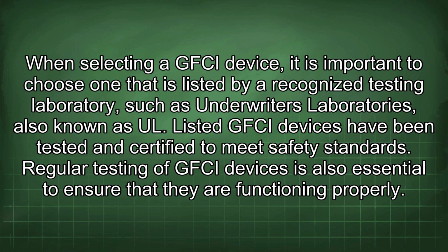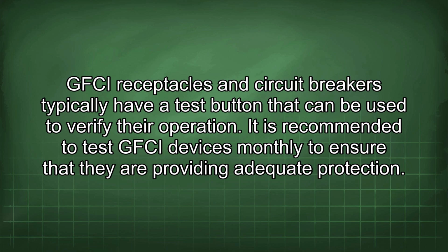Listed GFCI devices have been tested and certified to meet safety standards. Regular testing of GFCI devices is also essential to ensure that they are functioning properly. GFCI receptacles and circuit breakers typically have a test button that can be used to verify their operation. It is recommended to test GFCI devices monthly to ensure that they are providing adequate protection.